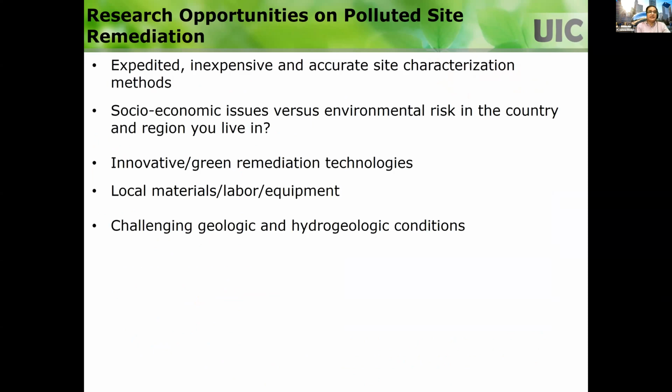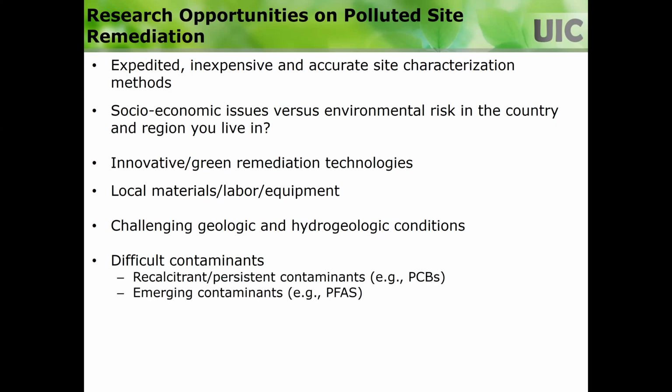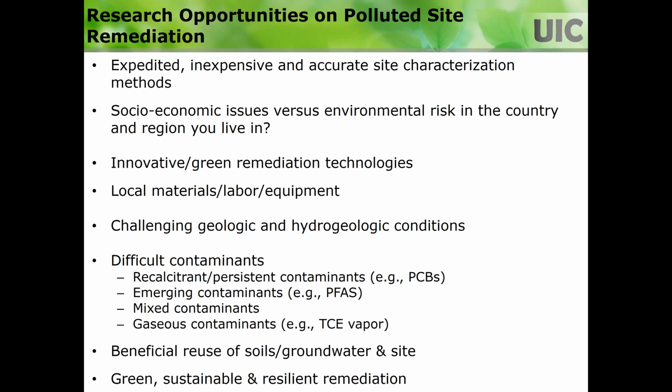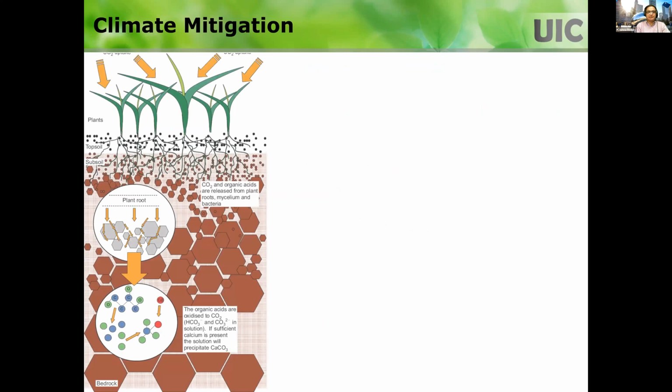So again, in India, contaminated site remediation hasn't gotten a lot of attention. I know there are a lot of sites. We need to have good techniques to do the site characterization, right? First, you need to know if the site is contaminated, how much of the site, and what kind of contamination you have. Then you have to do the risk assessment based on the socio-economic conditions, and think about remediation technologies based on the contamination and the resources that you have. So again, learn from what is done in other countries and then tailor them to meet the local needs.